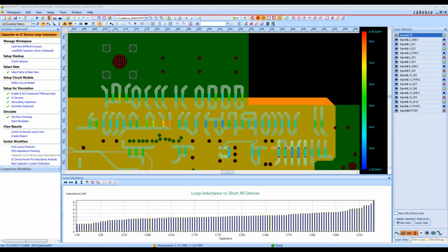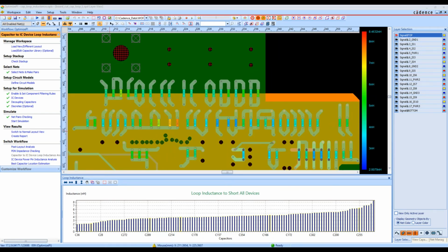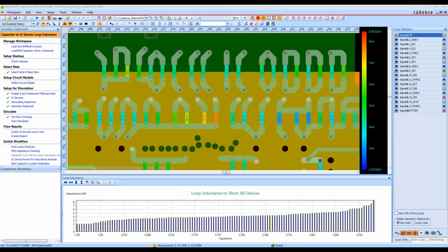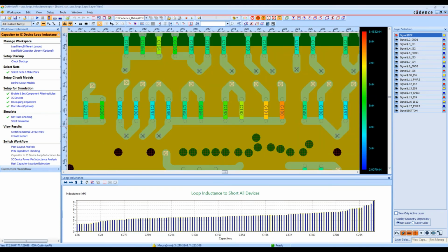There are some examples right here where a via is shared. Normally that's not really better. You would like those vias to be as close as possible. The benefit is for space saving, reduced holes in your planes, and reduced vias used. The detriment to your power integrity is that it increases your loop inductance, which is not desirable.